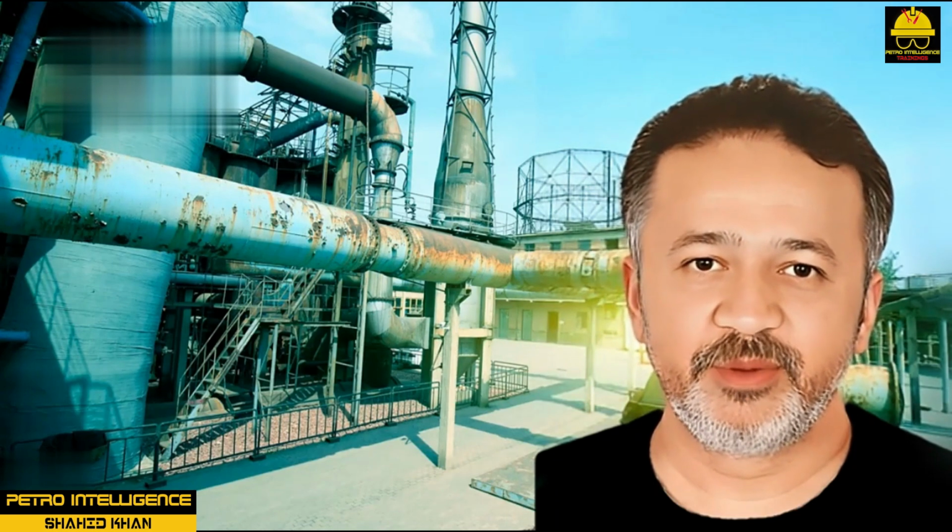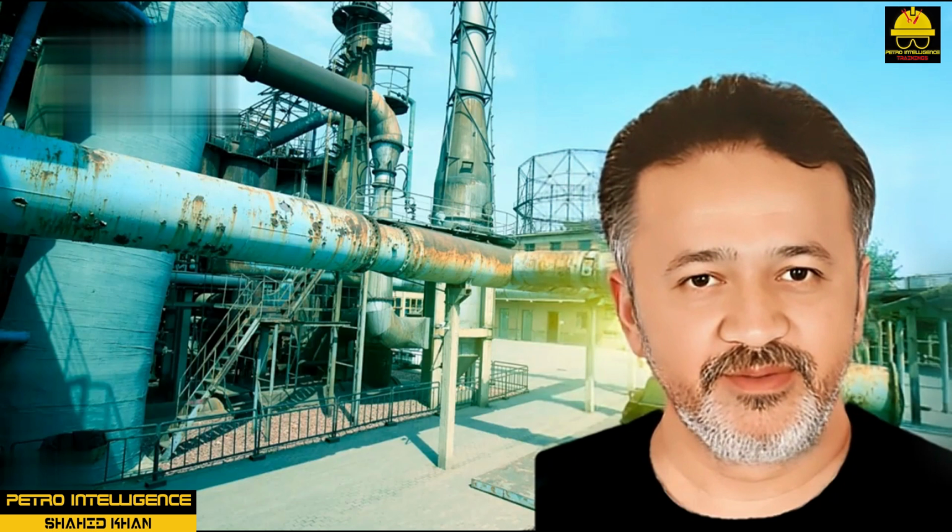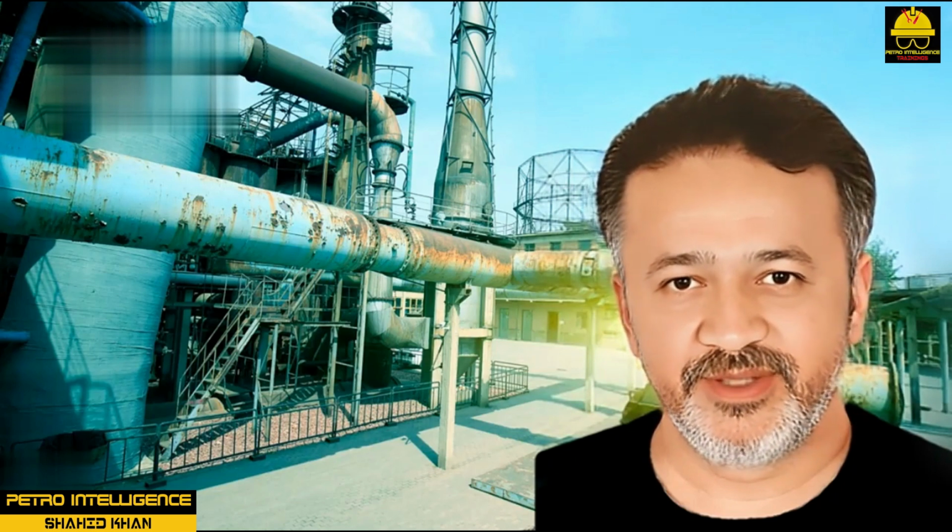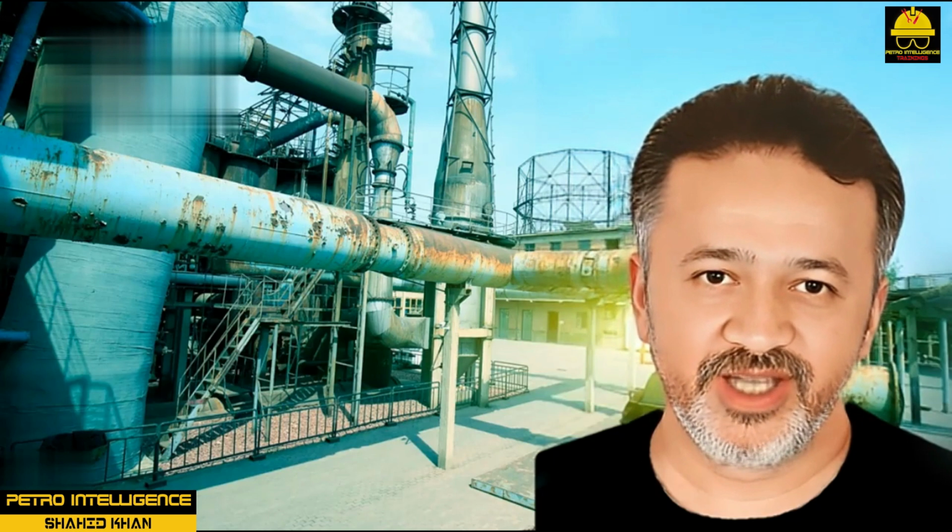Hot relief system, hot flare. The hot relief system collects liquids and vapors from units that operate above 32 degrees Fahrenheit or 0 degrees Celsius. The flare header branches throughout the plant and terminates in a sloped line leading to the flare knockout drum. The knockout drum is a carbon steel vessel that contains a steam coil to vaporize light materials and to warm up heavy materials so they can be pumped to recovery.